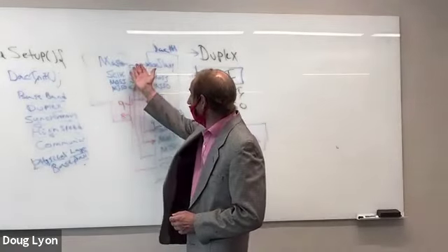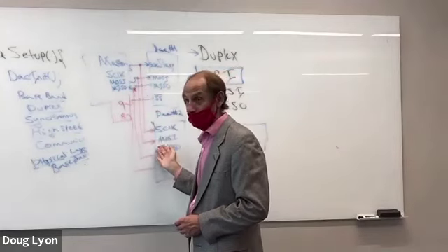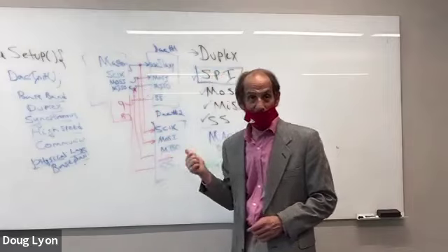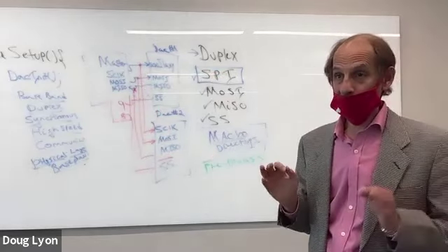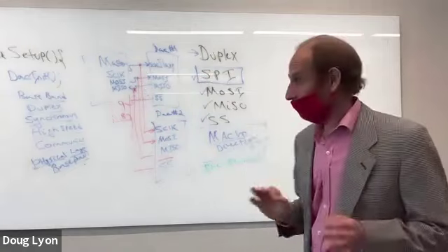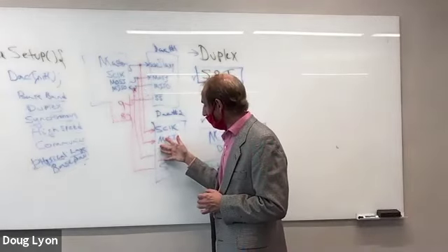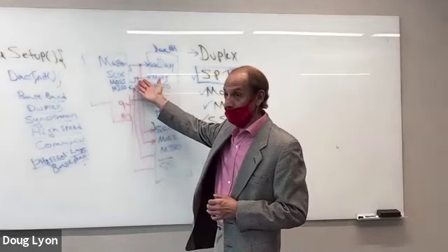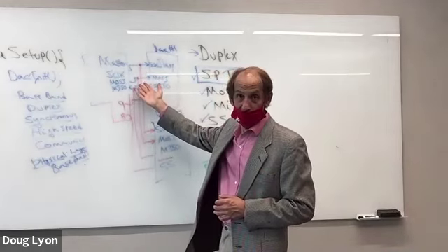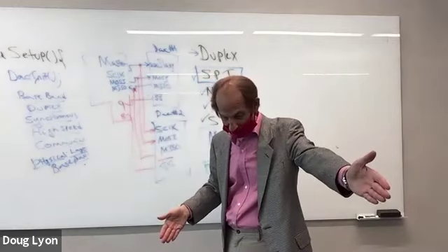Because when you start to wire different devices to the same wires like this and then select which device you're using, that makes it into a bus. And busing requires a tri-state logic system. That is, busing requires that you be able to take a device and put it into a high impedance state so it does not assert the lines. Because if 2 devices assert the lines at the same time, one device can say you're a 0, and the other device can say, no, you're a 1.